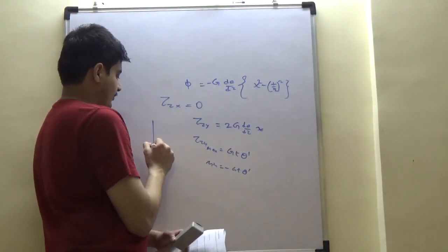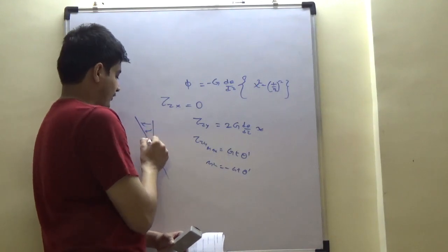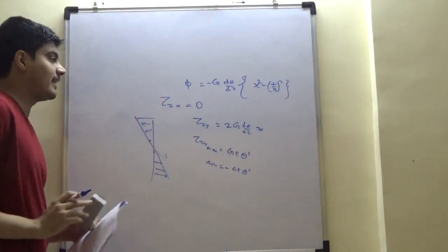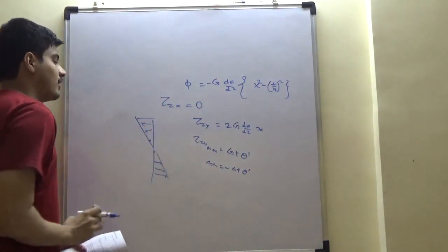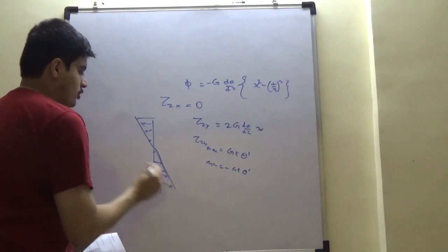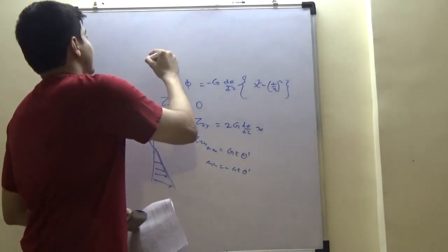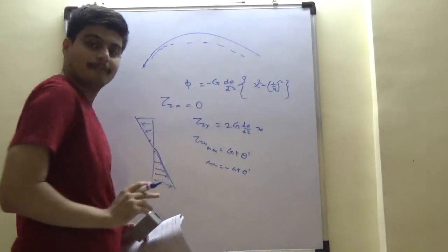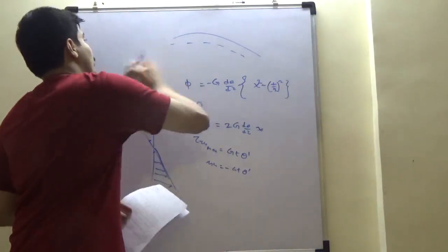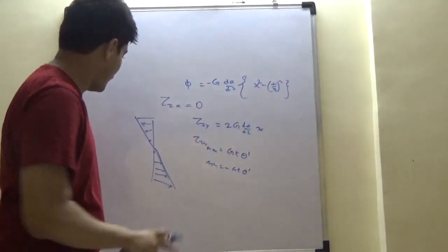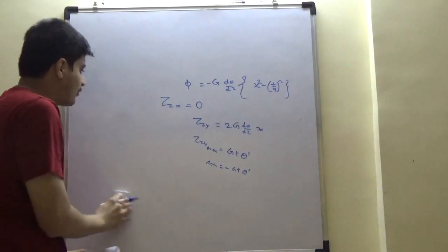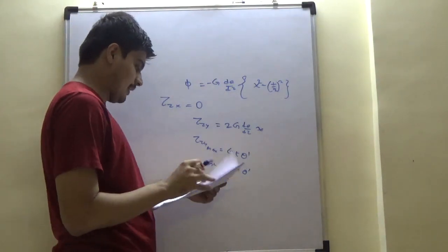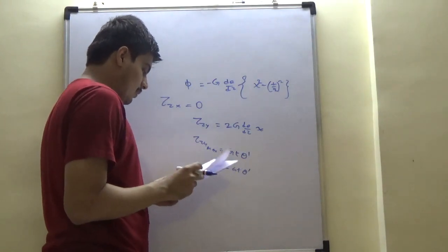So it is this variation. It follows this linearity. This is also clear from warping, it has to go from negative to positive. In warping, when the bulge was W, N becomes something like this. That's how it holds, the projection component. So again, the membrane analogy is helping us to correlate back and validate from a physics point of view, intuitively, whether this is right. So this is clear, tau zy is now clear.